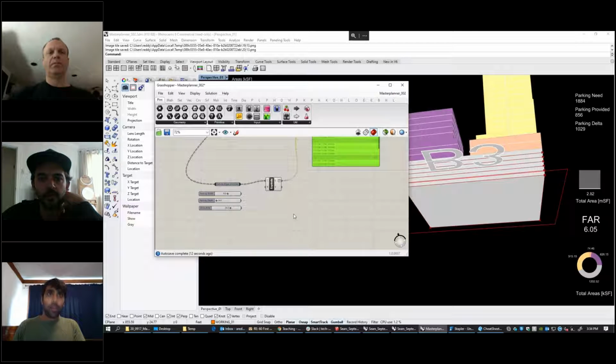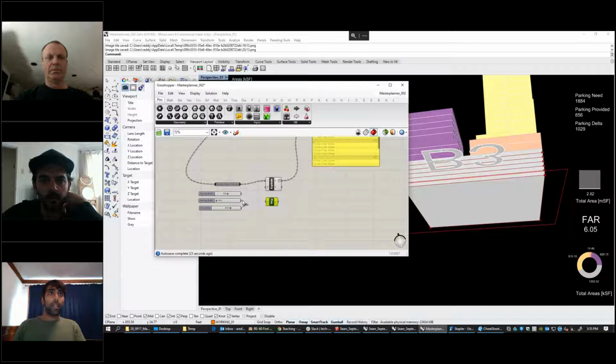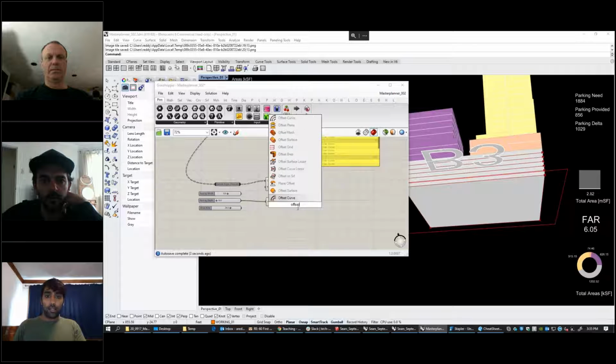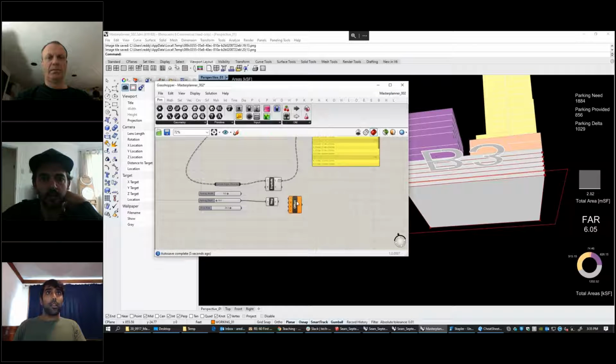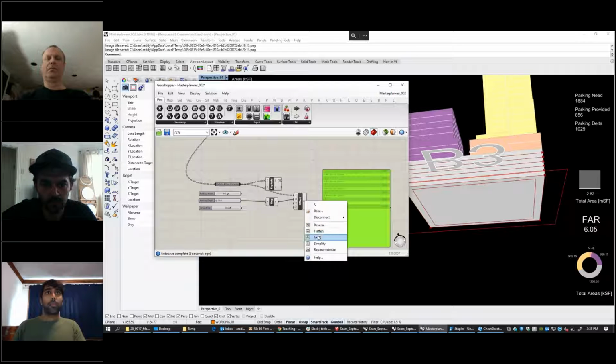And then to get the inside edge, you just want to offset that outside edge. So we're going to use a negative 18, and then offset the outside geometry, these outside edges, by a negative amount. So now in the same way, we've still got these same, I'm going to simplify them.